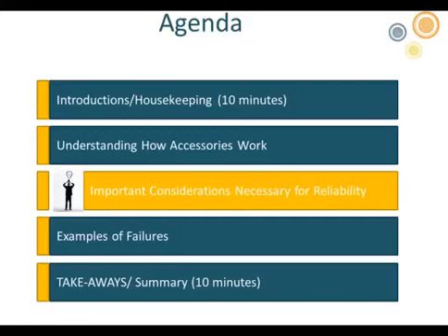Ken would like to know, how much tolerance do terminations and splices have for positioning over the end of the semicon on the cable? That's a good question. It depends on the manufacturer partly. Some of us put more tolerance in than others. For our particular ones, we like to see a minimum overlap on the semicon of the stress control material of 1/2 inch.